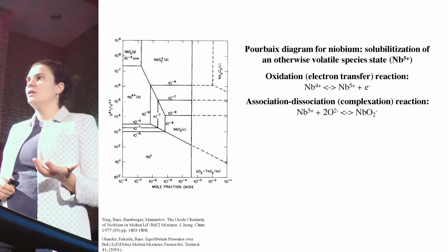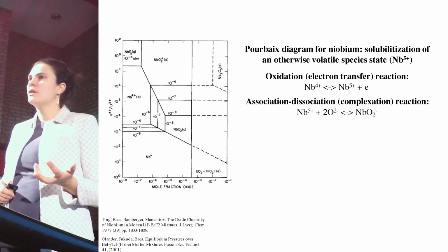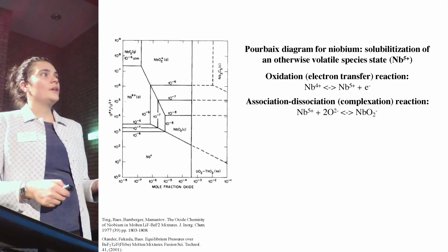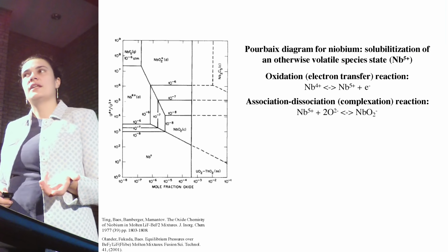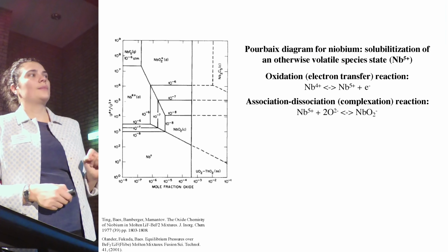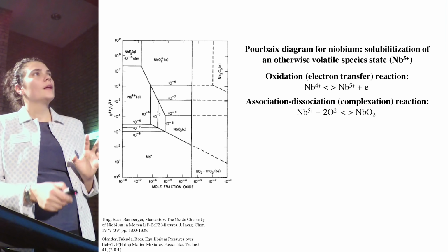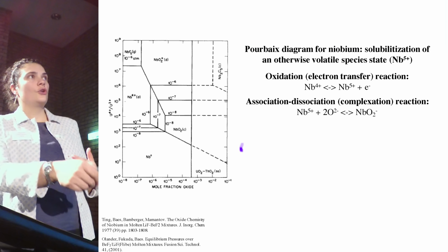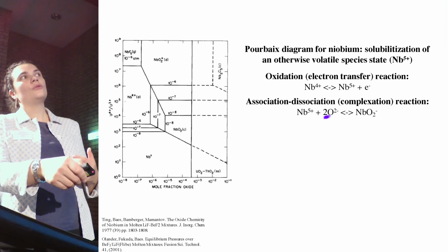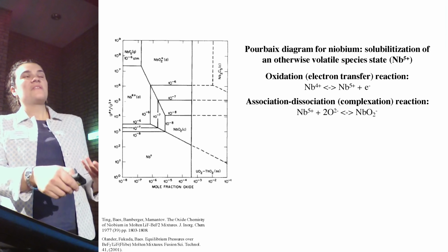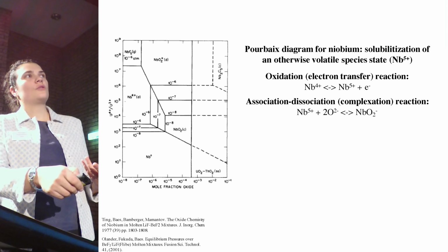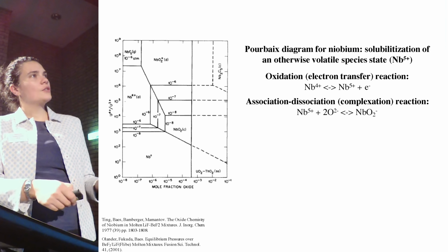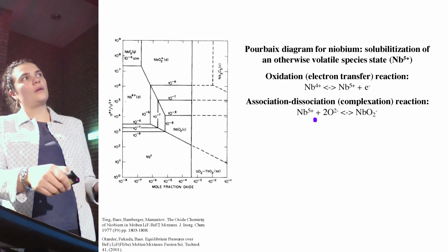And we would call these diagrams Pourbaix diagrams, and we would use them in predicting corrosion of metals. In molten salts, we do not have Pourbaix diagrams. This is not a Pourbaix diagram. This is a pseudo-Pourbaix diagram. Because in a Pourbaix diagram, we would quantify pH, which would be pO2-. But we don't have methods for measuring pO2- in molten halides. What was measured here was the total sum of O2-